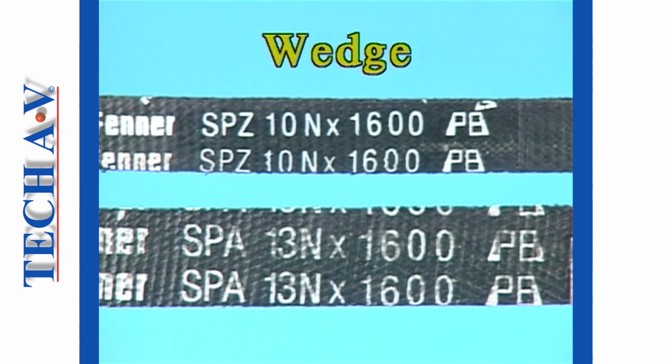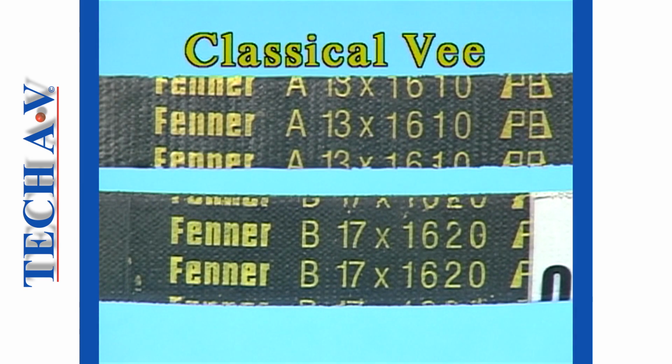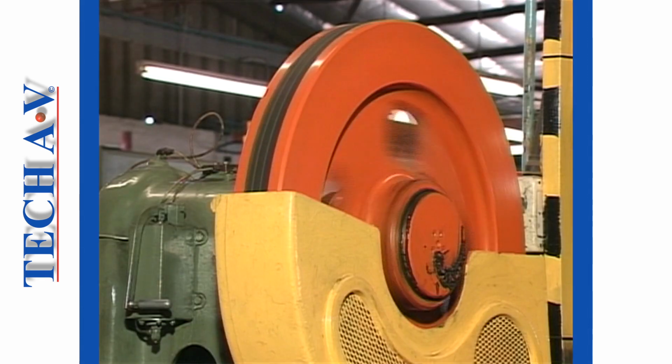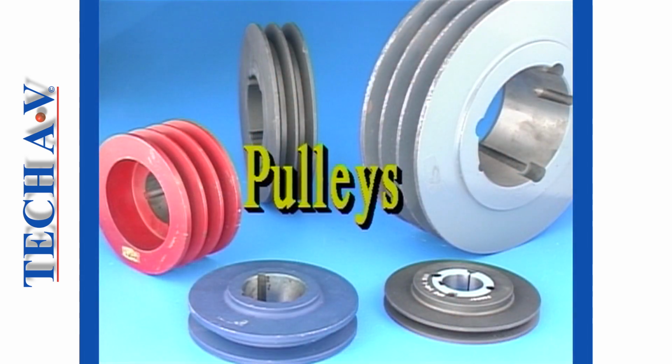So, to recap briefly, a wedge belt is identified by the letters SP followed by an A, B, C, Z or delta, and a classical V is identified by a single letter A, B, C or D. In modern industry, there is a move to standardize with the wedge-type belts, owing to their superior frictional properties and greater load potential. Let's take a moment now to discuss pulleys as used in general industrial situations.